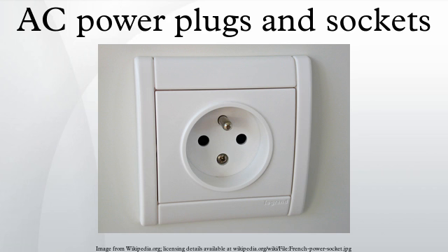Polarized pre-fitted plugs on appliances are therefore connected with the brown to the right pin and the blue to the left, the earth being connected to the hole at the top of the plug. CEE 7/4 plugs are not compatible with the CEE 7/5 socket because earthing in the CEE 7/5 socket is via a round male pin permanently mounted in the socket.